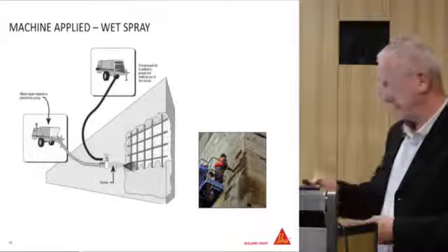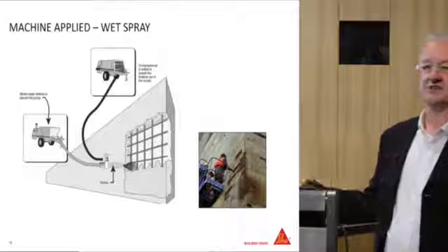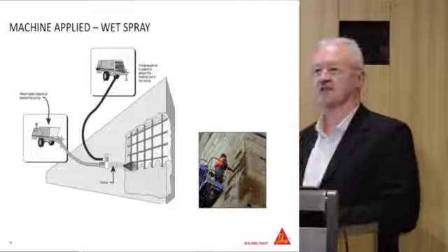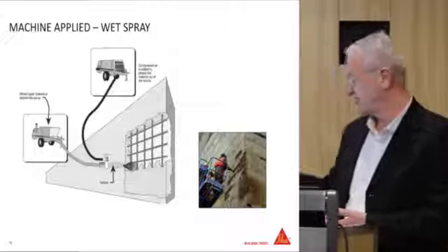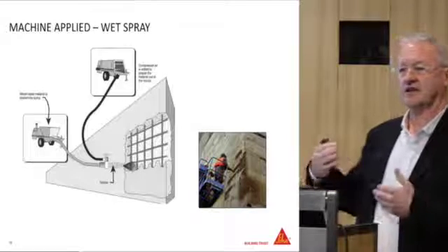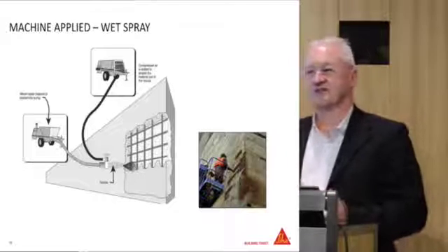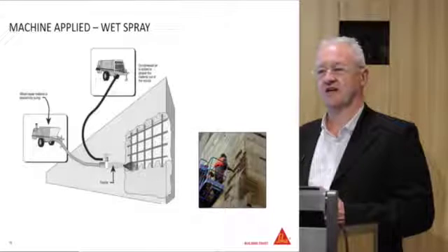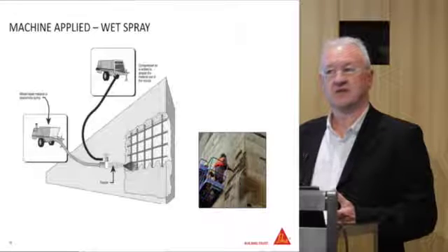And again, you can see there are quite a few repairs here, and the contractor decided that rather than have a guy doing hand placed, it was going to be more productive to use a wet method of application, because he could fill the repairs up very, very quickly. It's really a case of when you get to site, sometimes you don't know how big these repairs are going to be, and a lot of it has to come down to contractor choice from the point of view of how he's going to apply that material.